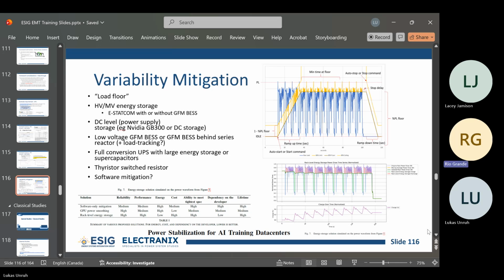So it could make sense to tier them and hold bigger plants to higher standards. That's kind of what NERC does with their bulk electric system definition, right? Those connected at a significant kV level at a significant size, which was above 115 kV, or sorry, 75 MVA over 115 kV.